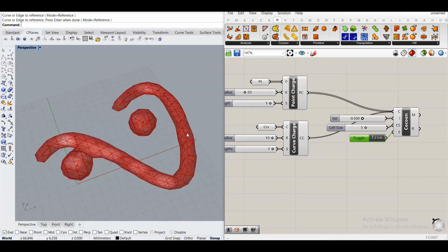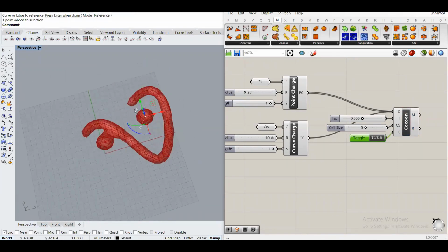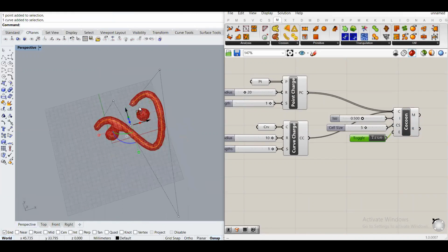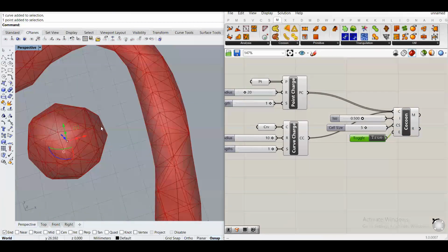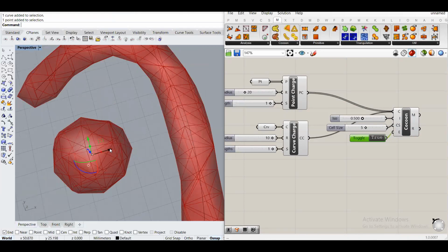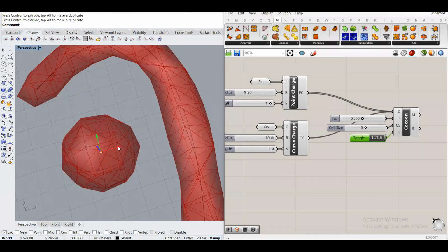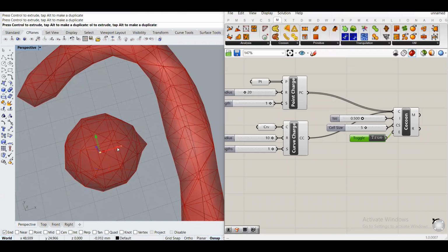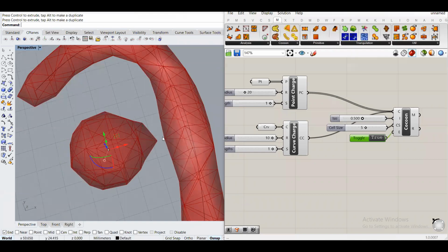but as I always say, you need to start off with low resolution so that you have a higher degree of control. And then once you kind of know what's going on, you can increase the resolution, right? So in this case, let me show how it behaves. Let me grab the point here and let me slowly move it closer and closer to the curve. See how as I move the point towards the curve, the whole thing starts stretching out.